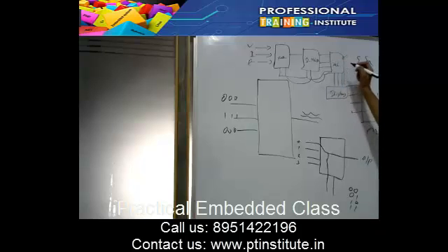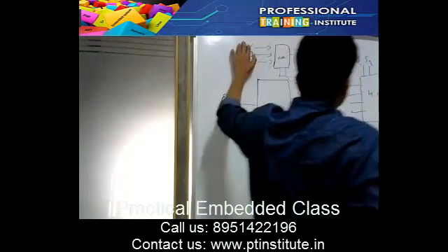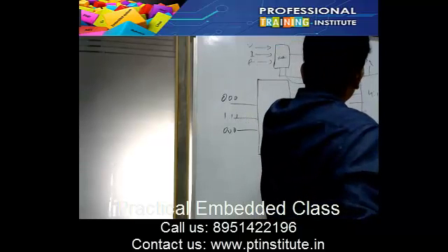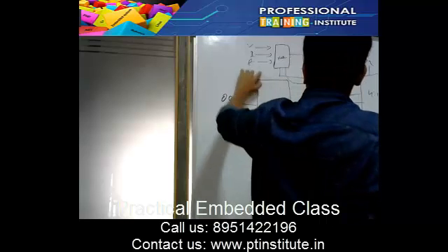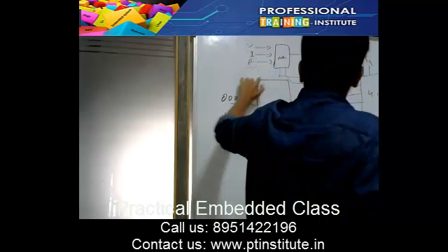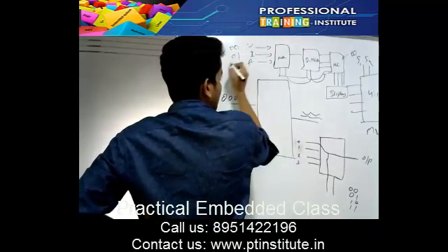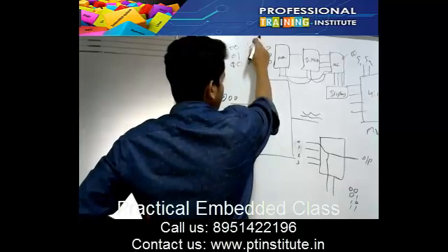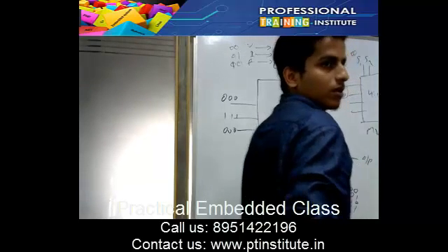If I give 0 0 and want to select voltage, what will happen? The selection I give to the demultiplexer also goes to the mux selection line. It is 0 0 for voltage, 0 1 for current and 1 0 for frequency, and it will select voltage. And this voltage will go to the mux. Fine. Very good.